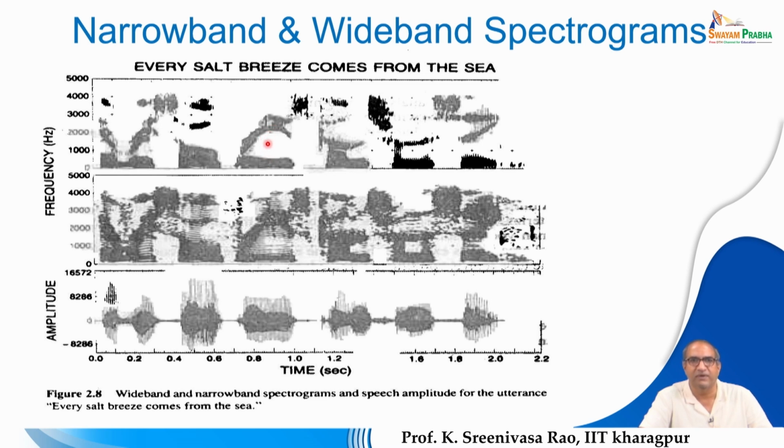It means the other frequency components, from about 300 to close to 2000, have very insignificant energy, very little compared to this one. And again around 2000 to 2500 we have some frequencies with energy, but lower than this energy. That's why here they are much darker, and here the darkness is somewhat less. And above 2500 Hz there is no visible frequency component.